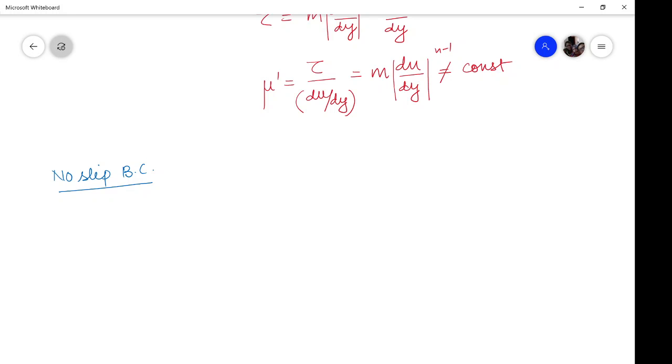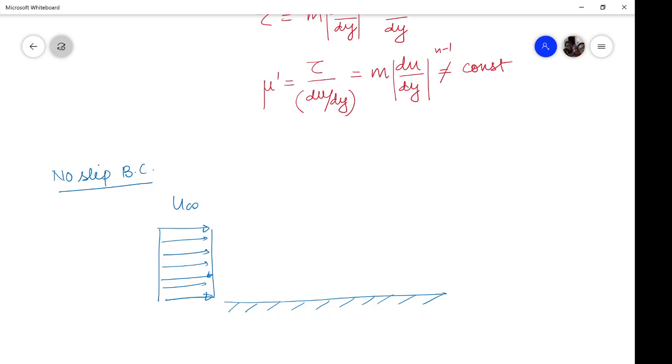That means if this is the solid surface and the fluid arrives potentially, that means no variation in velocity is there, like this. Then the moment fluid comes onto the surface of solid, it will instantaneously be retarded to the velocity of solid surface itself. That means the velocity of the fluid at the solid surface relative to this surface is 0.